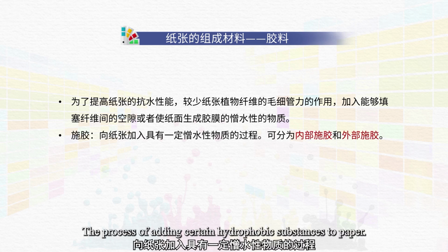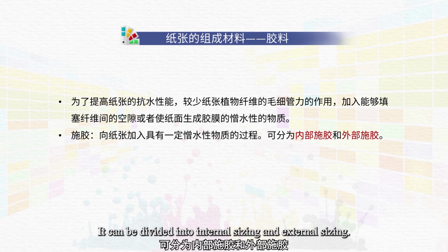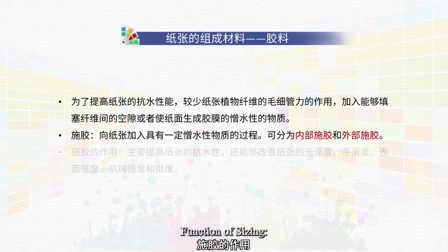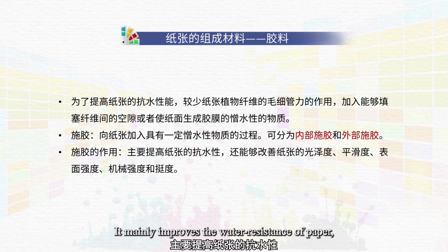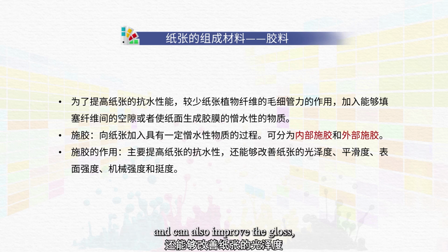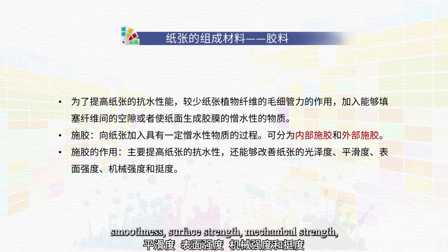Sizing: the process of adding certain hydrophobic substances to paper. It can be divided into internal sizing and external sizing. Function of sizing: it mainly improves the water resistance of paper and can also improve the gloss, smoothness, surface strength, mechanical strength, and stiffness of the paper.